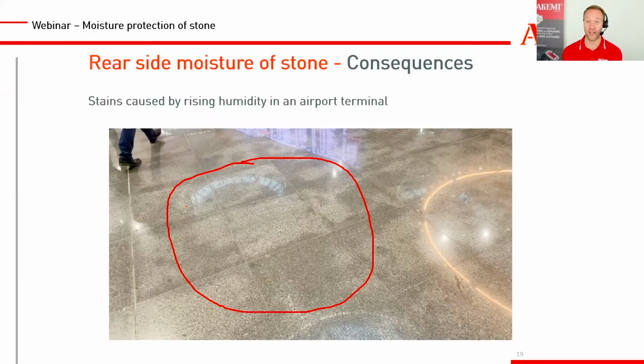Of course, big projects are always in a hurry. They have opening dates scheduled. So probably the installation companies will not wait till the substructure is completely cured, 28 days and so on. And they use maybe some special cements or mortars, which make it a little bit faster. So all this can cause staining of the stone later on. And it's a shame that already in the beginning of the project, the stone is ruined, and actually you should remove it and replace it.